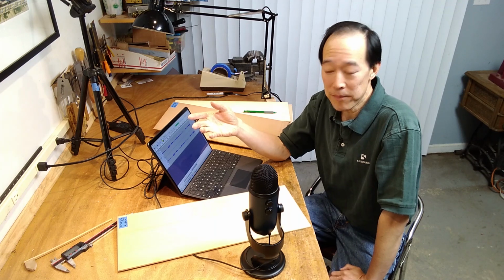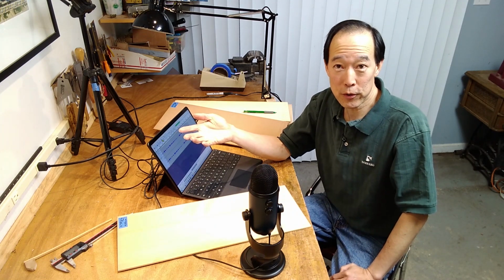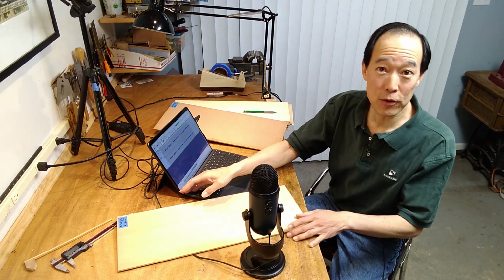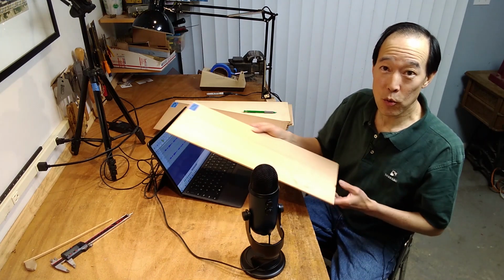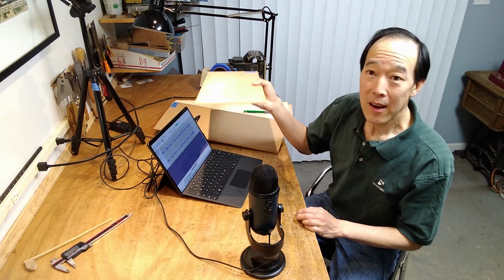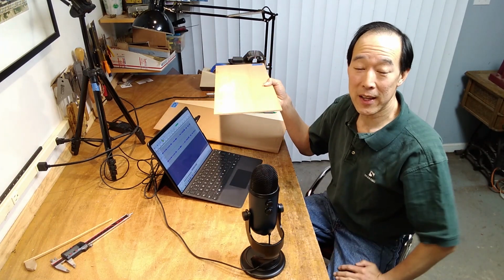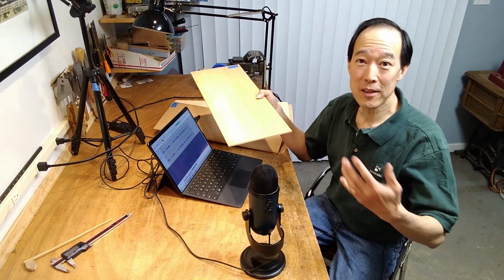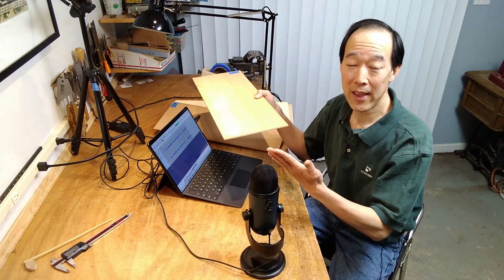Okay, so one of the first things that I'm going to do is to check for the vertical grain, which we talked about in episode 4, which is produced by radial cutting. So by vertical grain, or also known as quarter sawing, I want perfectly vertical grain which is perpendicular to the face of the soundboard. And you can select pretty quickly based on that.